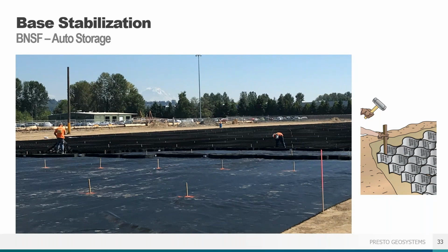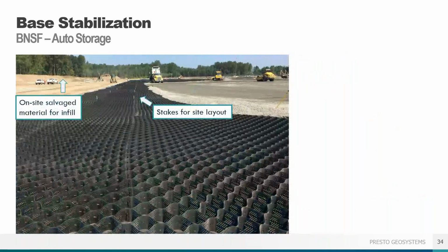Similar to using stretcher frames to open panels to a set distance, and we'll get to stretcher frames a little bit later, this hold open and the initial survey and staking made such a large installation go very quickly and very efficiently. Here we see a picture of the installation ongoing with a 4-inch wear surface to allow construction access during the installation. And again, using the GEOWEB system as its own access road for construction.